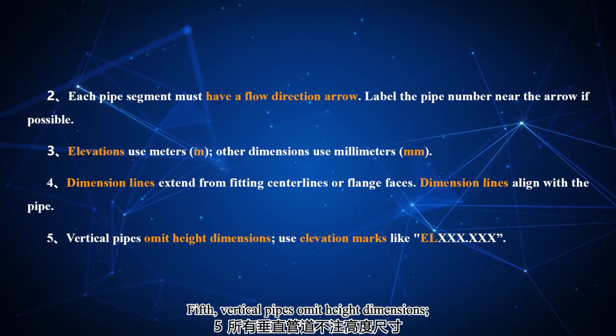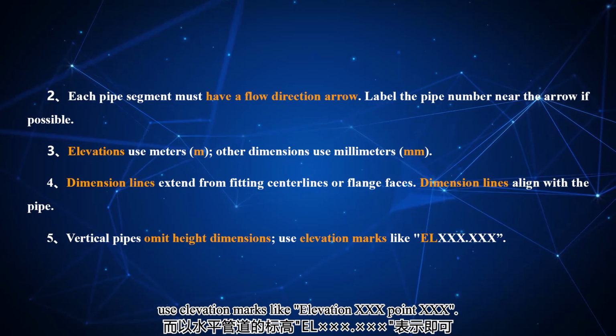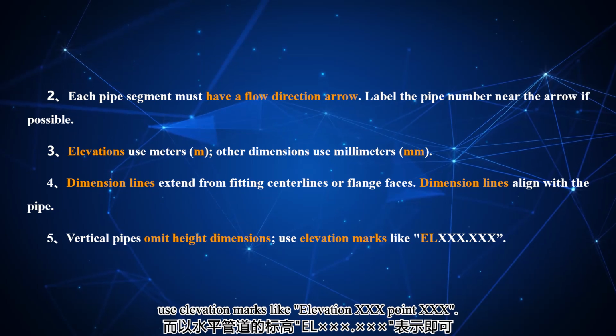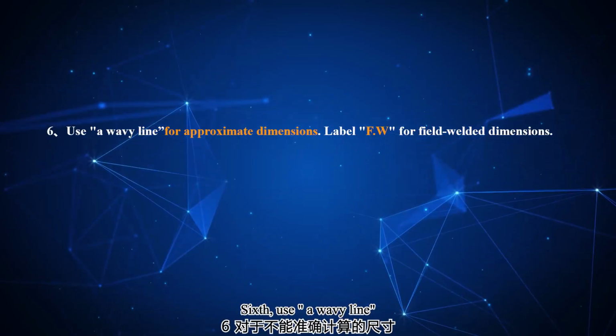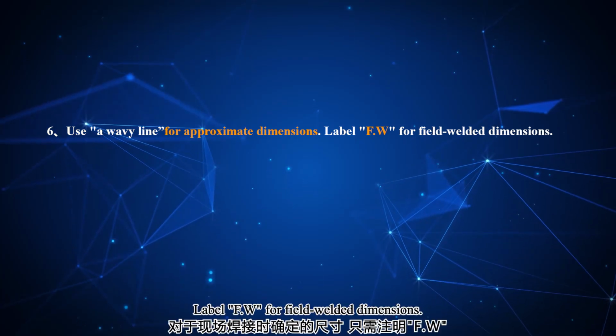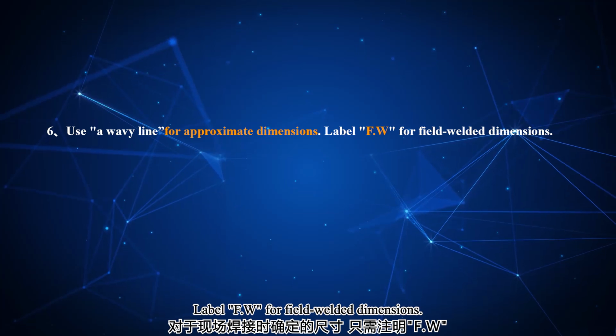Fifth, vertical pipes omit height dimensions. Use elevation marks, like elevation X, XX point, X, XX. Sixth, use a wavy line for approximate dimensions, label F.W for field welded dimensions.